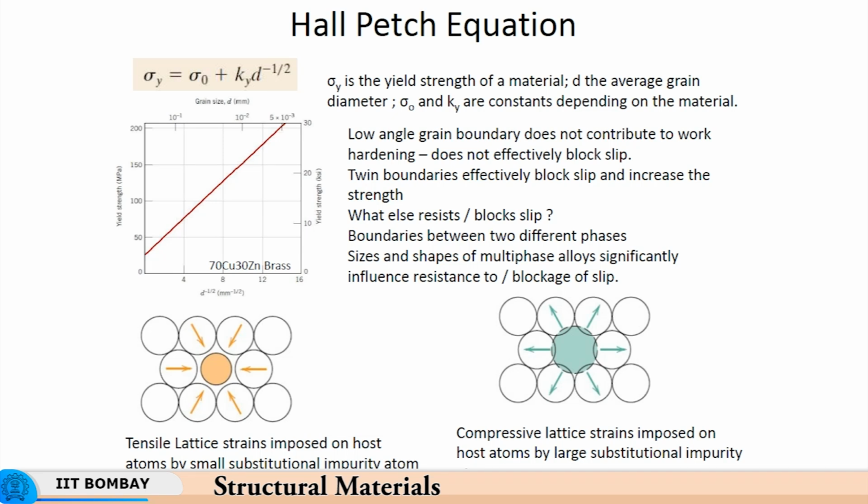So this is a very important equation, and this applies only for temperatures which are below equicohesive temperature, where there is dislocation activity. So this characterizes the work hardening due to dislocation activity, dislocation movement. Now if you take nanocrystalline materials, the size effects play a role, and therefore this equation will not apply.